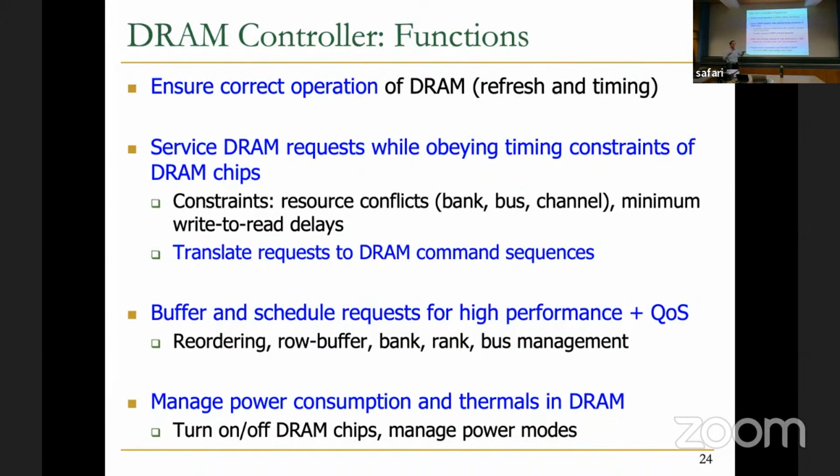And in modern system on chips, actually, it's not just that. It's not just 3D stacked DRAM. You usually have this system on a chip stacked on top of the DRAM. As a result, you have basically a big heat generator, which is the system on a chip, heating your DRAM, right? So basically, the power and thermals become a bigger issue in modern SoCs.